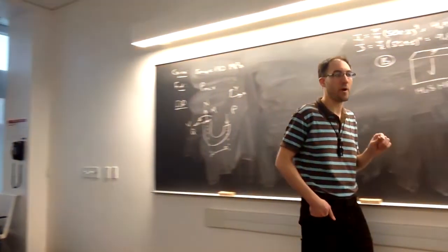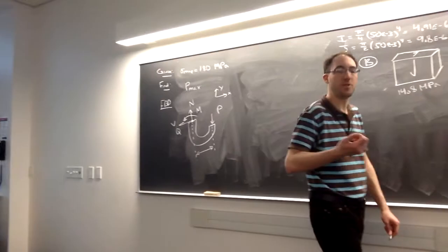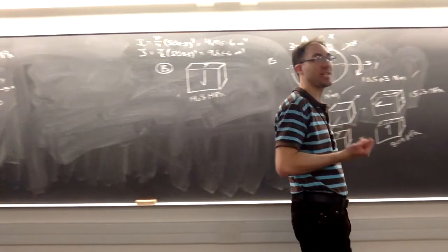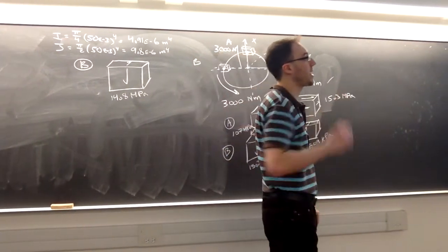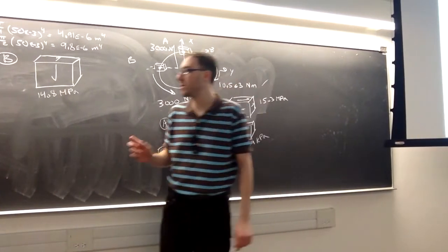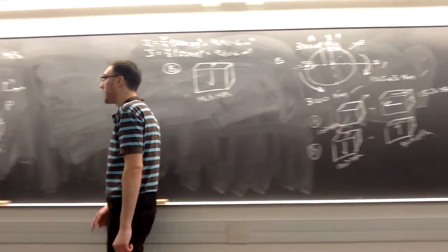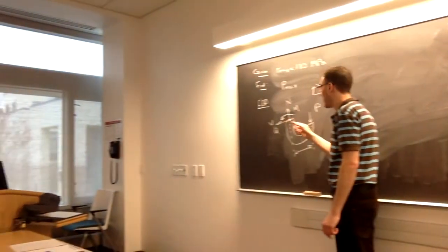What's our assumption of where the internal loads act from? We always assume that the forces emanate from the centroid of our cross section. So we're only told it's 200 millimeters to that right edge of it. We need to find where is the centroid first before we know how far these loads are from point P.